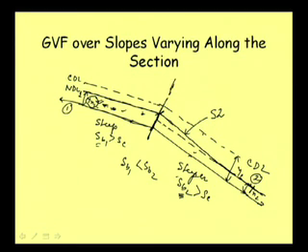So y0 is equal to yn1, and from here we start computing in the downstream direction, and we will keep on going till our y is just greater than or equal to yn2. Well, that is how we need to know how the profile will be forming first, and then only we can compute the flow profile.